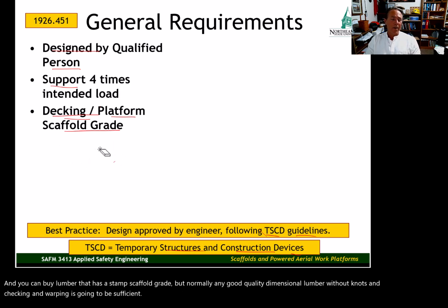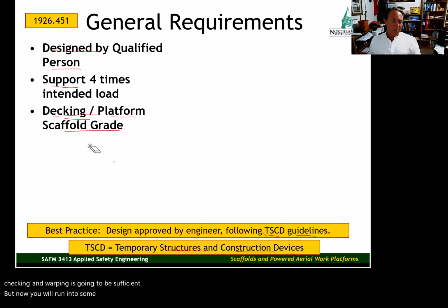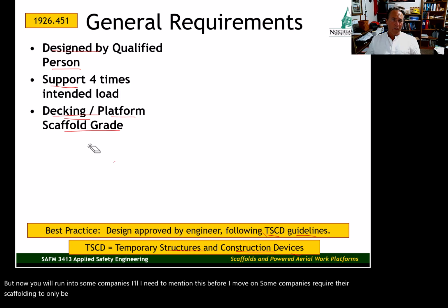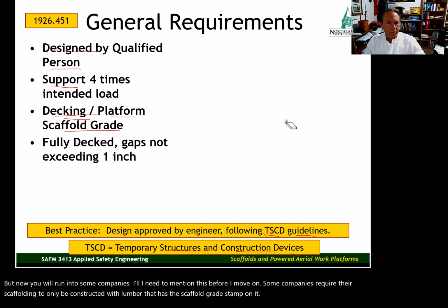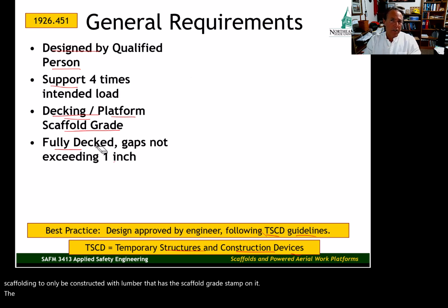But now you will run into some companies, I need to mention this before I move on. Some companies require their scaffolding to only be constructed with lumber that has the scaffold grade stamp on it. The deck, if you're using 2x8s, 2x10s, if you're using planking, it has to be fully decked with gaps not exceeding 1 inch.